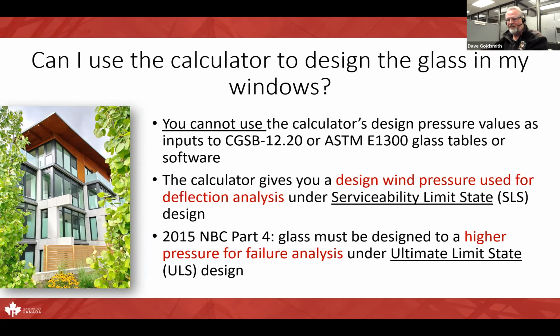And so designing with tempered glass, say you're tempering the glass for reasons like you need them to meet guard loads, the calculator will tell you, oh yeah, this is at 50% of capacity, but the deflection might be something that's not going to be acceptable to the customers.